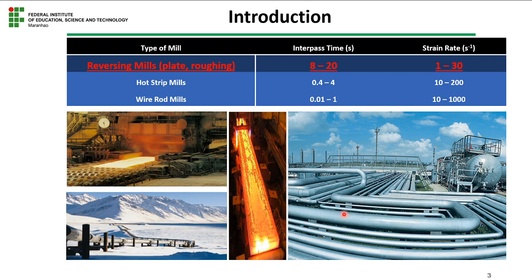The only way to control the mechanical properties of this grade is by the control of microstructure and crystallographic texture of this kind of steels. And this is possible by designing an appropriate chemical composition for this material and by an appropriate thermomechanical controlling process known as TMCP, that is, by applying the appropriate rolling reduction at the appropriate temperature and employing the right cooling rate.